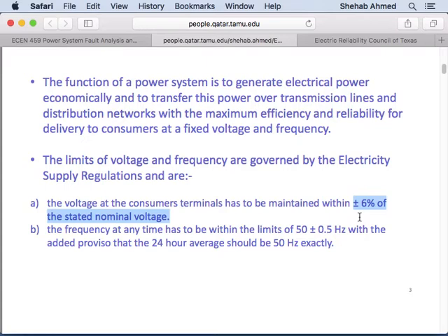And we said that big consumers, bulk consumers of power, will typically tap into the power system at higher voltages. Here we are tapping into the power system in this building. Downstairs in the parking lot, we have an 11 kilovolt to 480 volt transformer. This 11 kilovolt to 480 volt transformer belongs to Kahrama, right? Or actually, in this case, it belongs to Education City.